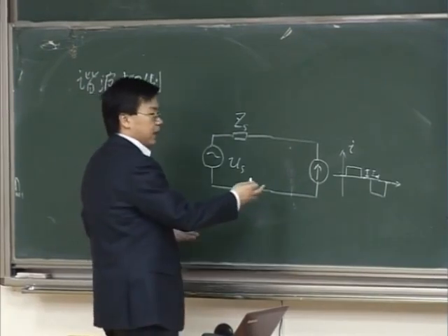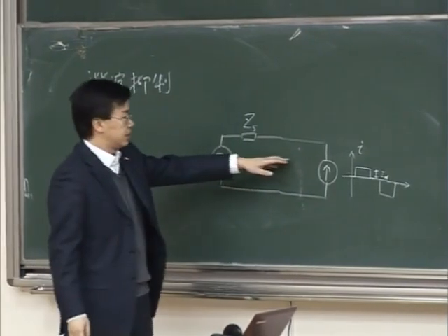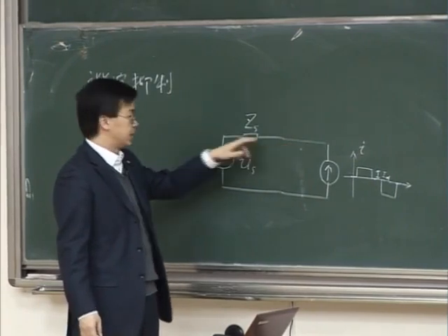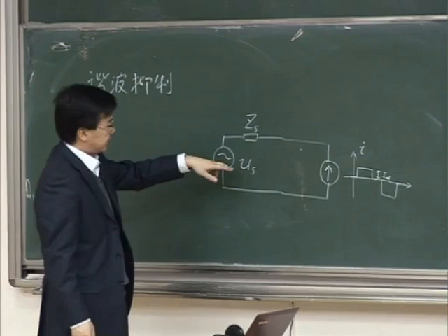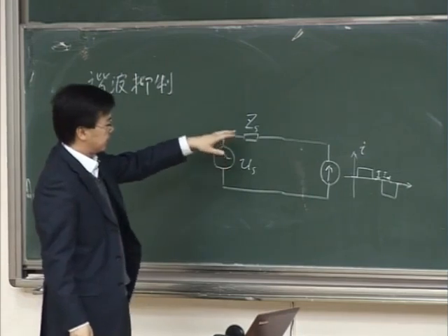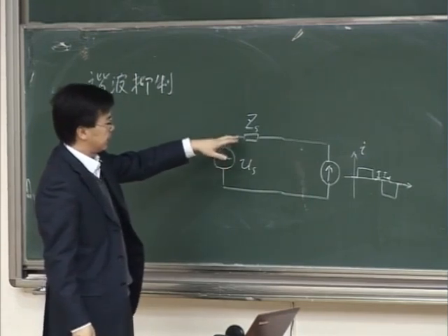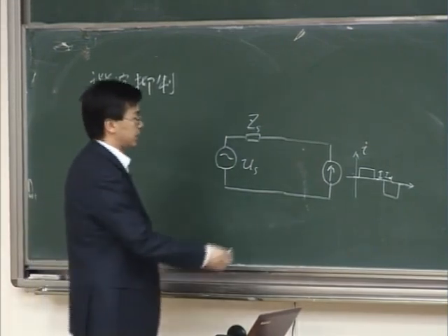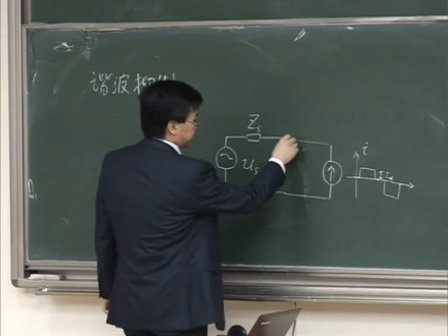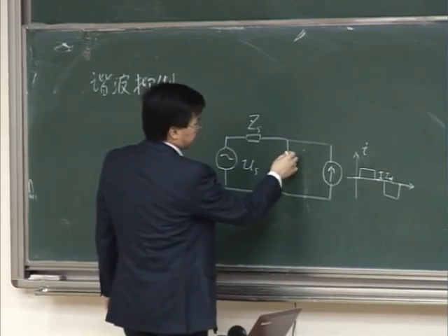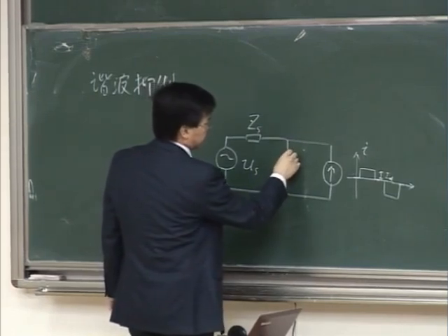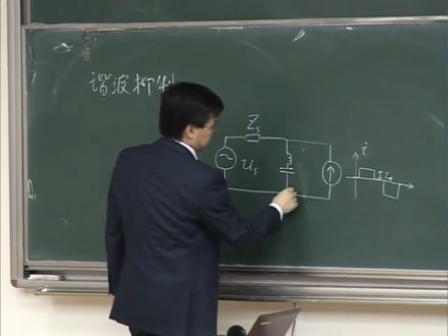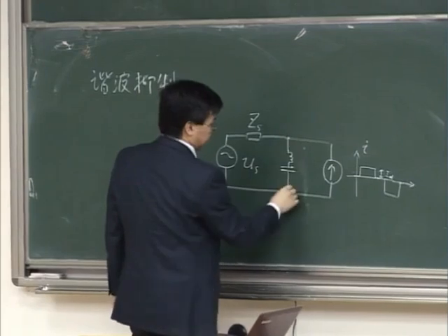Now I want to eliminate the current harmonics in the current flowing into the AC utility source. What I do is I can use a filter here. Let's say the traditional filter is an inductor in series with a capacitor. That's the traditional filter.